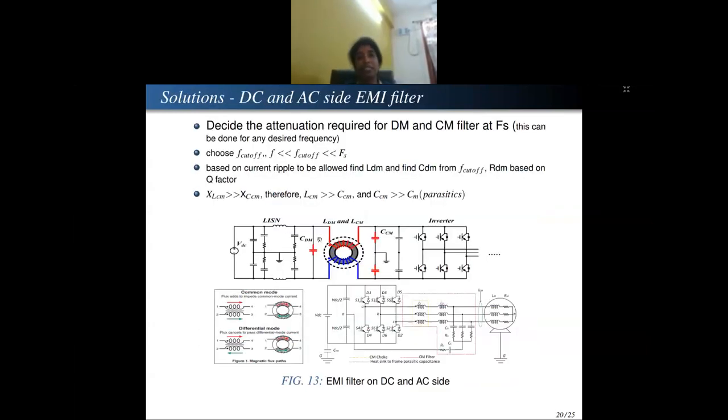Okay. Then next is the EMI filter. I had put only the EMI filter as the solution because, in fact, even filter people will not prefer it in the industries. People will mostly prefer what I have put here, the common mode choke. People would like to put either a choke or a filter because of its easy adaptation to the system.